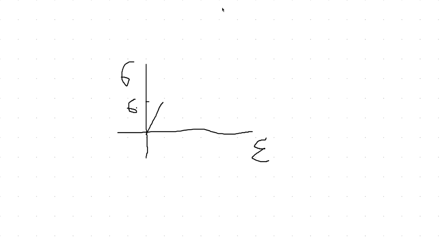And then I can go like that if you want. And you go there. So this is now a threshold of plasticity. So if you unload, if you have this isotropic hardening only, you're going to go to the same level as this height here, only for the negative value of sigma. However, in reality, many materials do not behave this way.